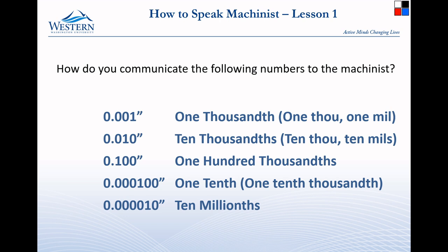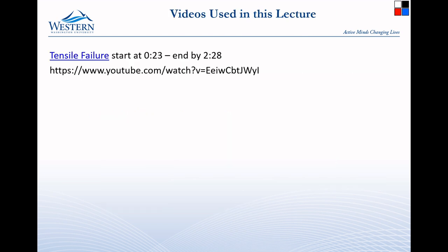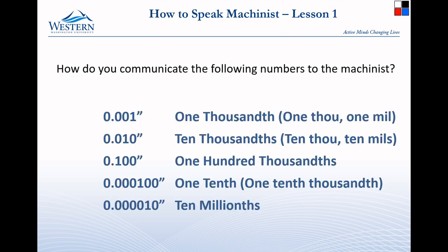And in fact, if you are in a shop that deals in millionths, then the one right above it, which we called the tenth before, becomes 100 millionths, if you are working in that sort of machine shop. There are not so many of those machine shops, and it may just be some processes, like grinding, can do millionths. Surface finish is often in millionths.